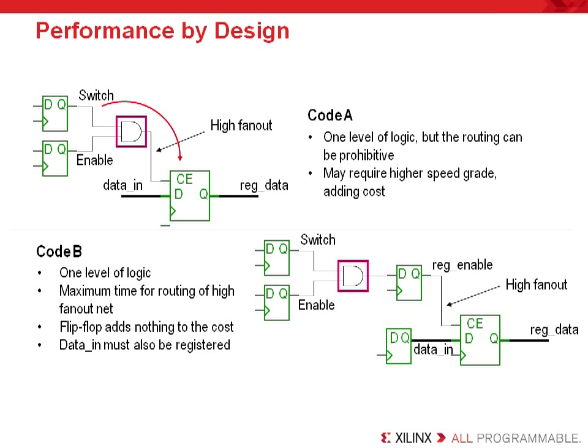This assures that the only delay between these two registers is just the high fan-out net delay, which can now be tolerated. An added benefit is that the period constraint will automatically constrain the paths between these flip-flops. A significant caveat to pipelining is the coding for the additional registers.